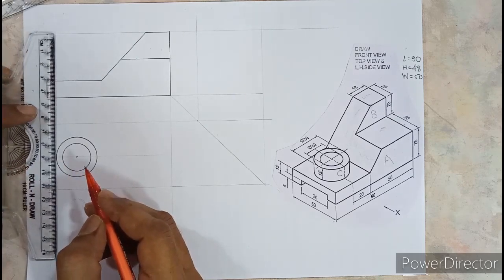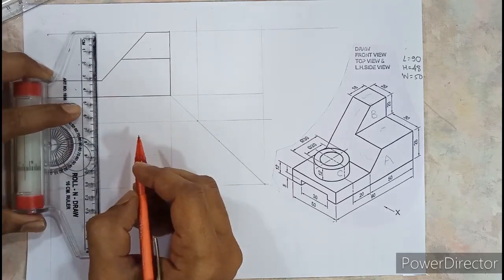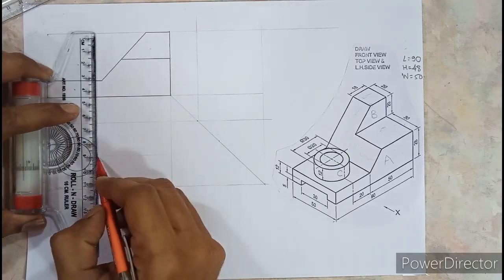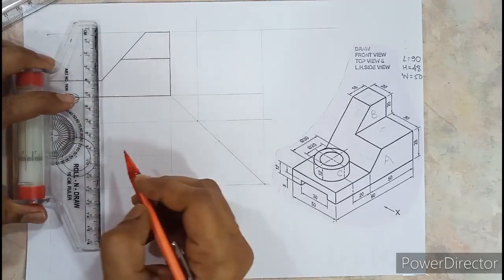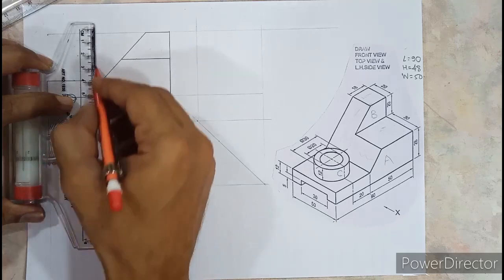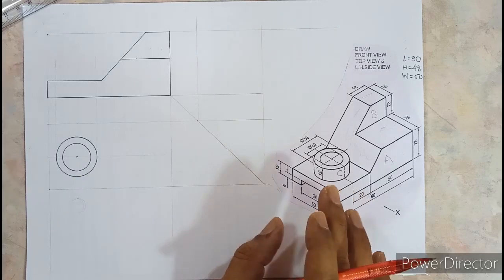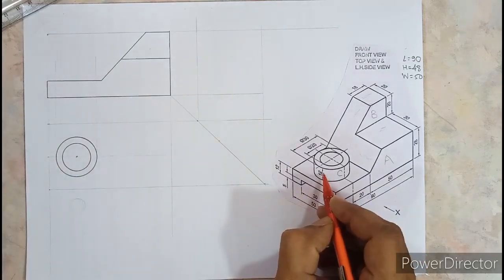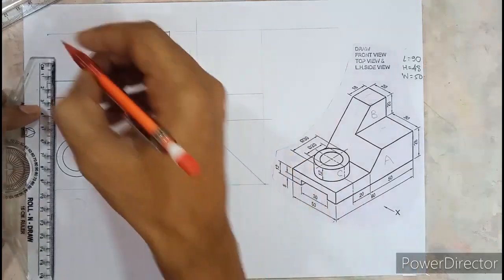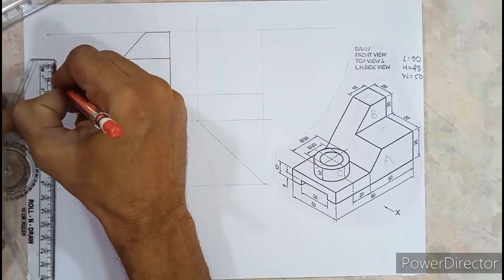you need to project this here. And this part will be seen like this. So I have projected the diameter of the cylinder here, because you can see this half as a rectangle. What is the height of the cylinder given in the question? It is given as 12 millimeter. So from here, you have to mark 12 millimeter. So double trace and darken it.